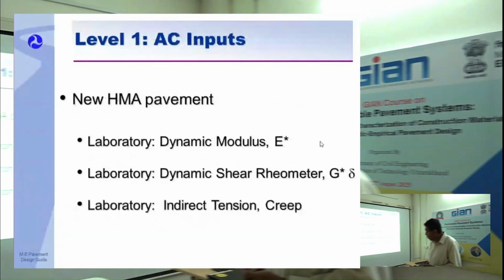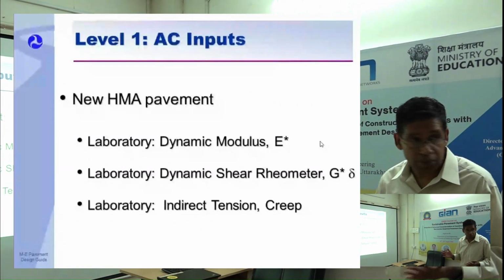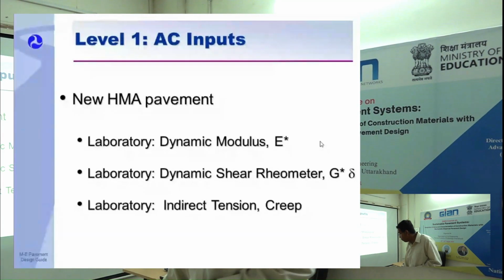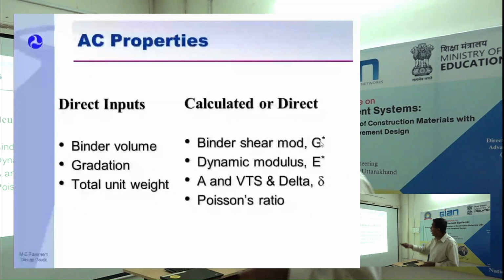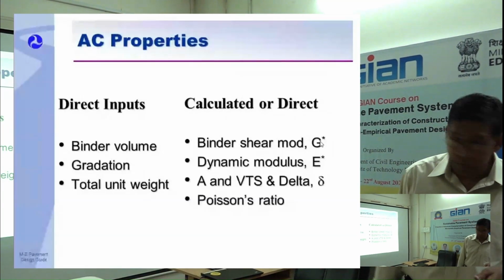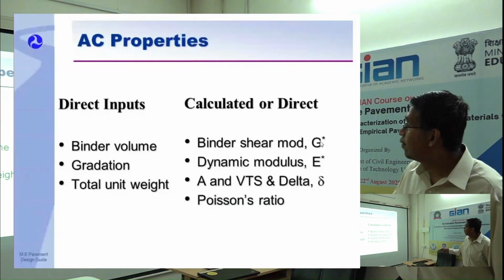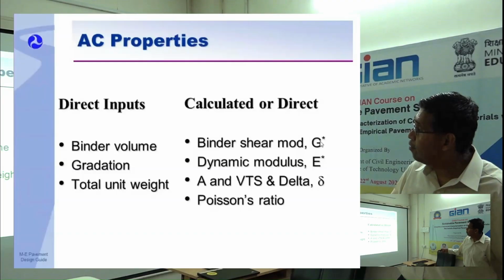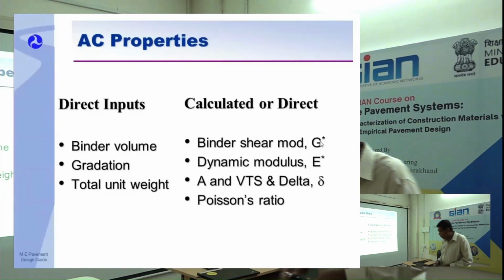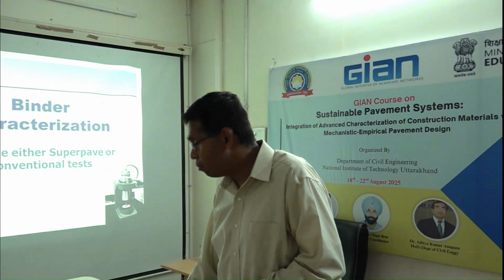New HMA pavements, we will talk about dynamic modulus, dynamic shear rheometer, and I can do some discussion about material properties as well within the context of the mix design. Direct properties, binder volume, gradation, and total unit weight. Right? Shear modulus, binder shear modulus, I think your student is measuring in DSR, right? Dynamic modulus, E star, phase angle, and Poisson's ratio. So if you guys are not aware of this, I can explain. Fine. We can start this later.